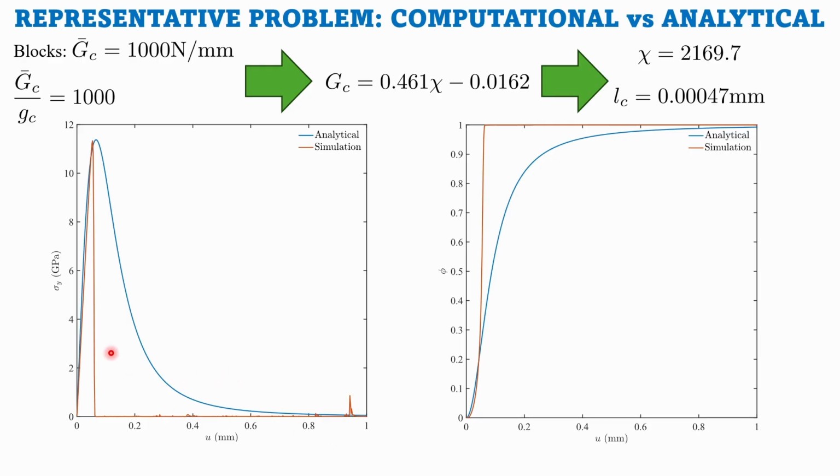Now you might think that these curves do not match, but for the analytical solution we neglected the second order derivative of phi, so those things make a difference. The analytical solution is just a one-dimensional solution, and what we are concerned about is this peak. Qualitatively, this scaling predicts the same peak as your actual phase field simulation.